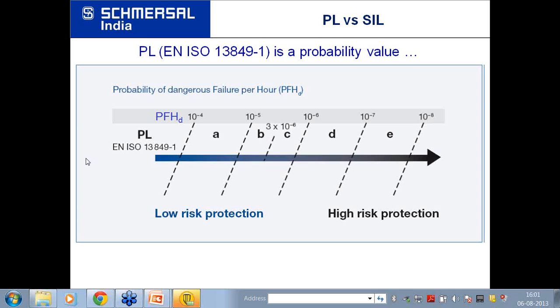So there were 6 to 7 levels. Similarly, in an aeroplane, you have at least 2 engines, and they are powered separately. So similarly, for oil and gas process industries, we need to have more and more redundancies in the system. The standards definitely will be different. What I have discussed, 13849-1, will not be applicable for oil and gas process industry. To some extent, IEC 61508 will be possible to answer your queries on this.